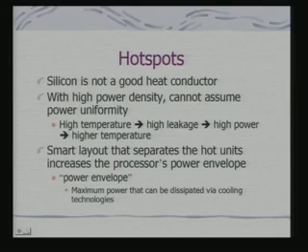The moment you place them close together, since they are being used intensively, the energy consumption over that area may be more, that is the temperature over those areas can increase. So, a basic objective of a power aware layout would be to have a smart layout, so that the hot units are distributed evenly over the chip area.